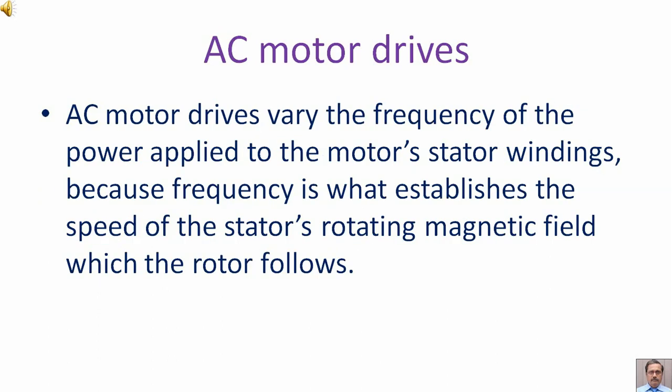AC motor drives. AC motor drives vary the frequency of the power applied to the motor's stator windings, because frequency is what establishes the speed of the stator's rotating magnetic field, which the rotor follows.